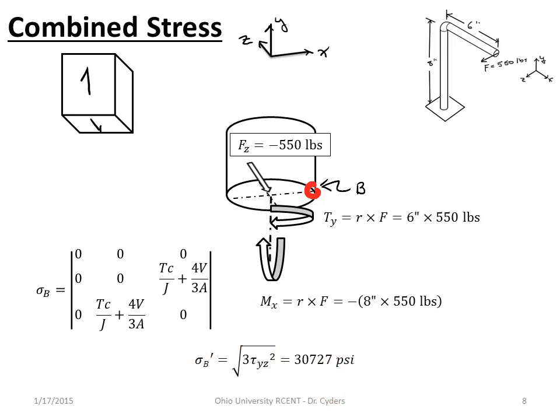And so that's how combined stresses work. We have to remember that combined stresses and combined forces, etc. If I were to put some other force on here, I have to remember to do my shear and bending moment diagrams to make sure that my stresses are already calculated. In other words, I can't just take one state of stress at B and then simply add it to some other state of stress due to a totally different load. I need the loads to balance first, and then I can go and calculate my stresses. So that's how combined stresses work.